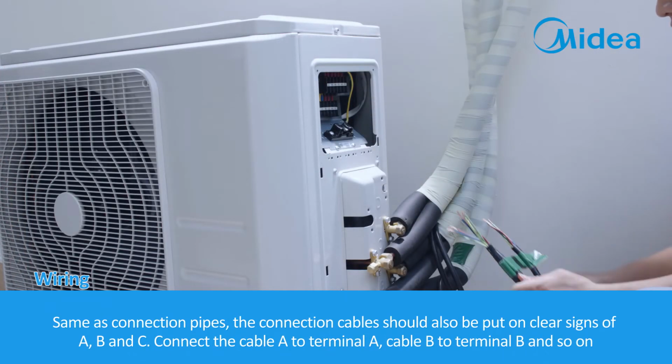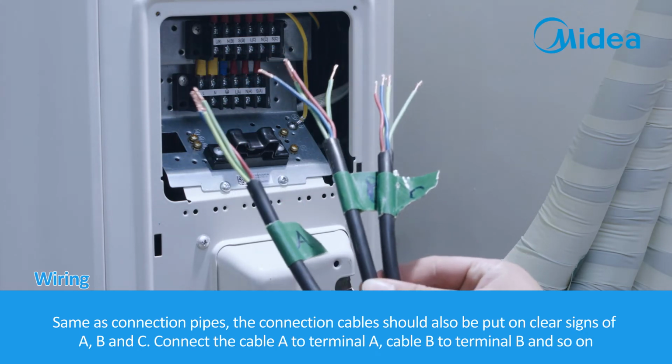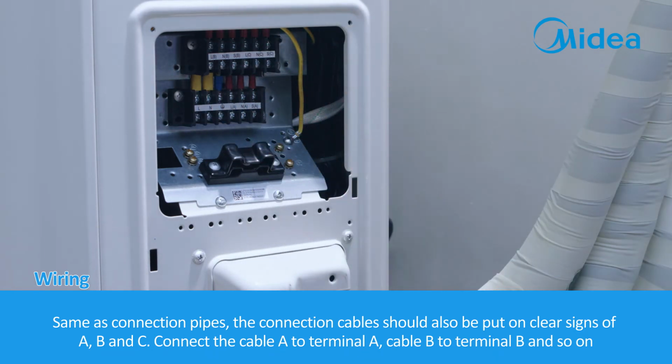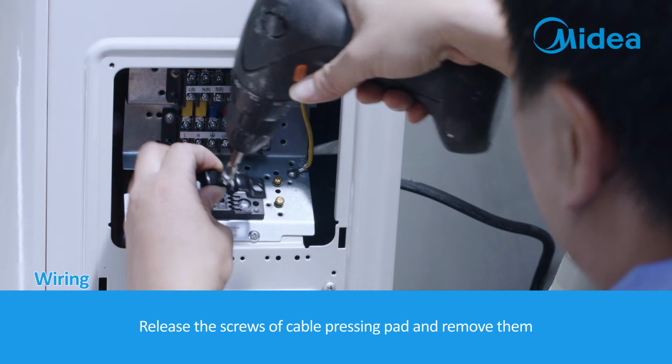Same as connection pipes, the connection cables should also be put on clear signs of A, B, and C. Connect the cable A to terminal A, cable B to terminal B, and so on. Release the screws of cable pressing pad and remove them.